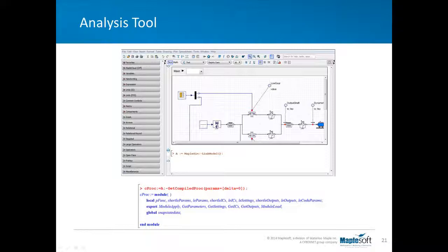So by knowing the relationship between the gear shifting, the vibration or disturbances, and the passenger comfort, the suitable set of values for the engage and disengage timings of the clutches can be obtained by doing repeated simulations for a number of iterations using different sets of parameters.